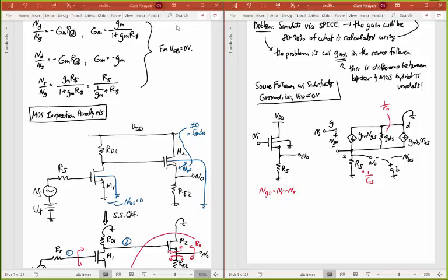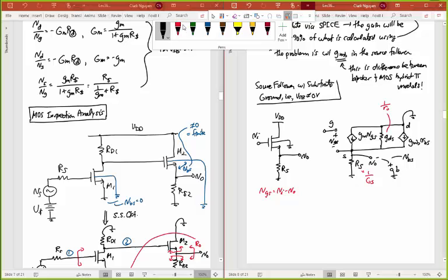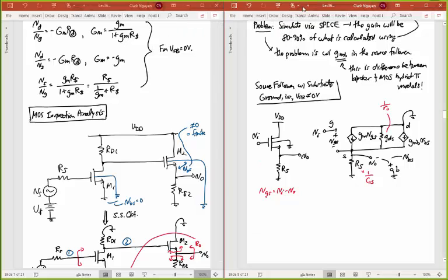You can see that right across here. If this is vi right there and that's vout there, I guess you can't even tell that's vi, so let me rewrite that to make it look like a vi. So I have vgs equal to vi minus vout. I also have vbs, that's just equal to minus vo, because of the polarities that I've drawn there.